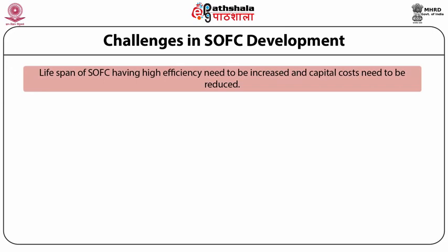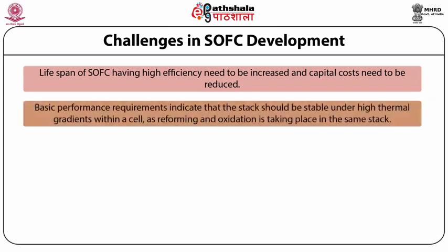These can be improved only if pre-reforming is not necessary and the electrodes give considerably less overpotential. Basic performance requirements indicate that the stack should be able to withstand high thermal gradients within a cell, as reforming and oxidation take place in the same stack.